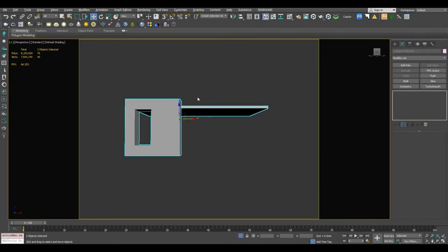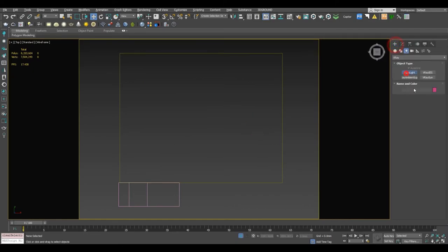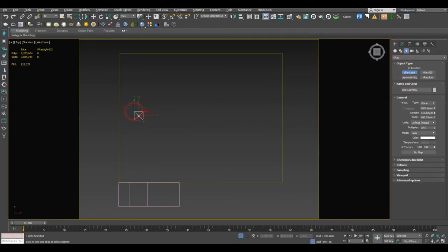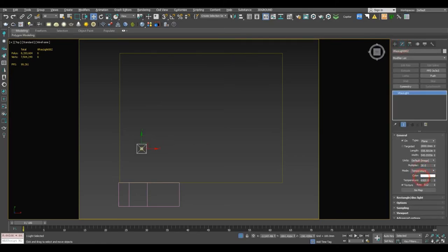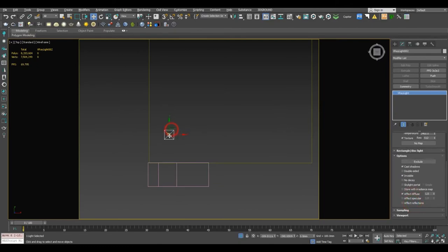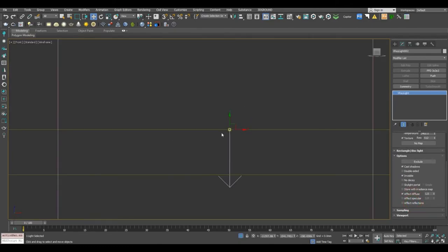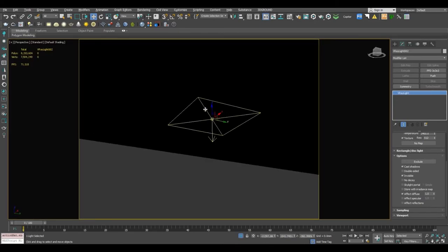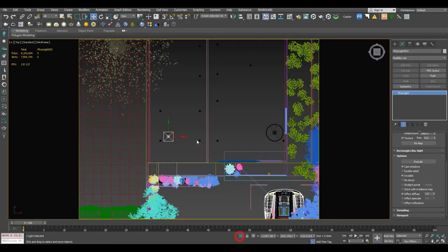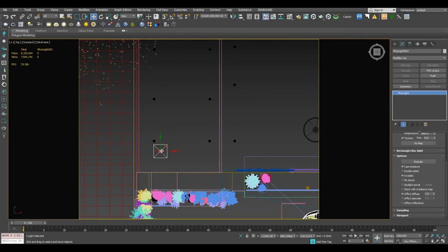Select the wall and top view. Click on Vray light. Add a Vray plane light. Select modify panel, set temperature for a warmer tone. Go to options, click on invisible and disable. Adjust our light. Shift and drag for a copy. Make it instance. Click OK.